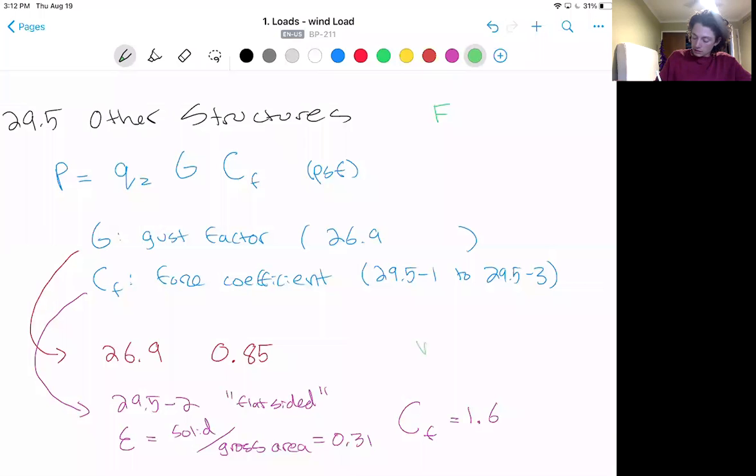This is using the W1 walkway detail, which is like our worst case scenario. It has the most exposed profile area. I won't go into the calculations in this lecture, but you can navigate to that detail and use the geometry to calculate how much solid area we have per gross area. And a good resource for calculating that is also added in this module as a textbook, and is a resource for calculating the solid area of chain link fence. Other than using those factors, it should be pretty easy to use the profile of the detail to then calculate what our total solid area to gross area ratio is.